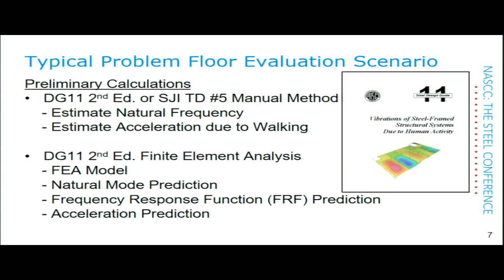If that's not the case, then there is a method in Design Guide 11, second edition, on how to use the finite element method to evaluate a floor. The process, of course, is to develop an FEA model, predict the natural mode, from which the natural frequency is obtained, and then do a frequency response function, FRF, prediction. From that, the acceleration prediction can be obtained. Dr. Davis will go through that in a little bit.